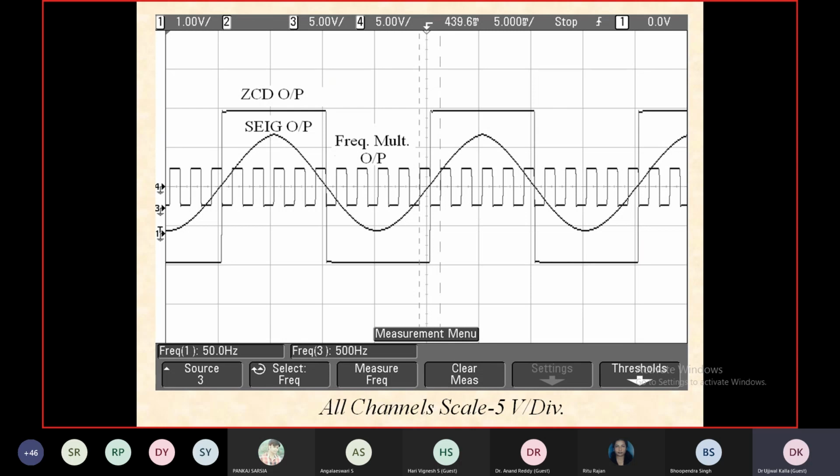Irrespective of whatever tuning skill you have for the PI controller, even with sliding mode control, there is definitely some steady state error, but with a PI controller usually the steady state error is always zero. But if you have a frequency multiplier in your system, and there is misalignment in this frequency multiplier, it will make your system so unstable that you will not be able to tune it. Steady state error will be there all the time, and your research will not be acceptable by the international community.